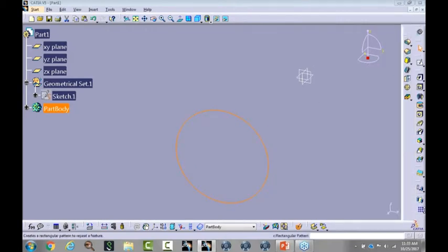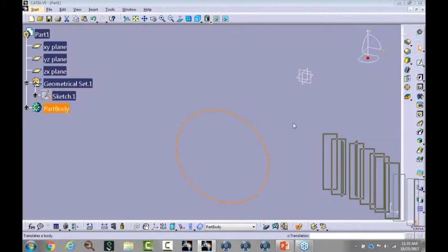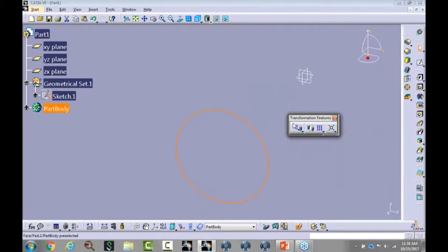Now, here's another little secret that few people realize, pardon the echoes. If you are dragging a toolbar, that's what I did there to create those echoes, and you hold down the shift key and release it, it will change the orientation from vertical to horizontal or vice versa. If you drag it into a toolbar area, it's going to do that automatically when it places it. But you want to get these things all arranged the way you like them. One thing that people tend to forget is you can put these on all four edges of the screen. So you can actually align the toolbars over here on the left edge also.